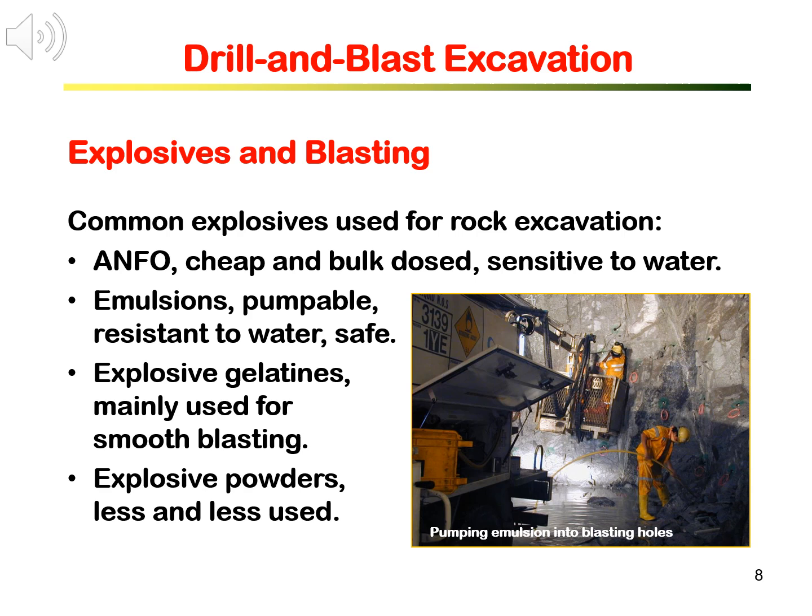Today, the common explosives used for rock excavation are ANFO. It is cheap and bulk dosed, but sensitive to water. Emulsion is pumpable, resistant to water, safe, and produces less toxic gases. Explosive gelatines are mainly used for smooth blasting. Explosive powders are getting less and less used.